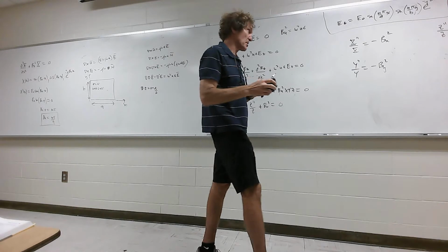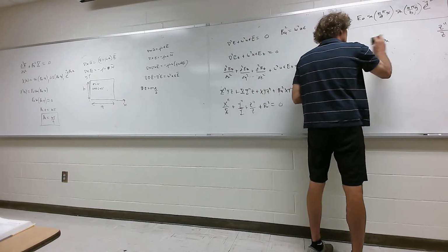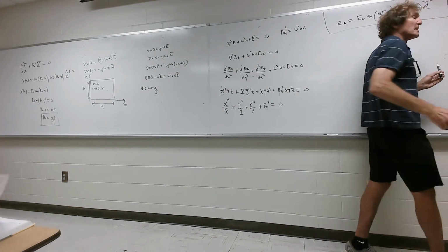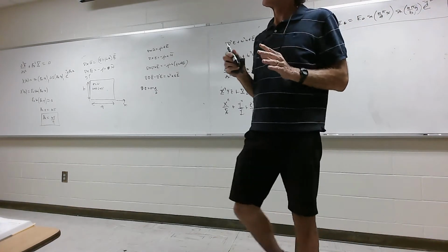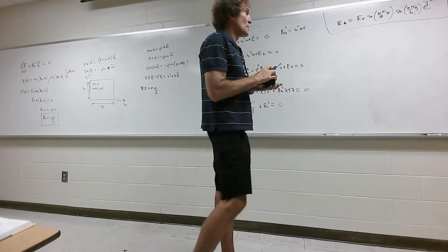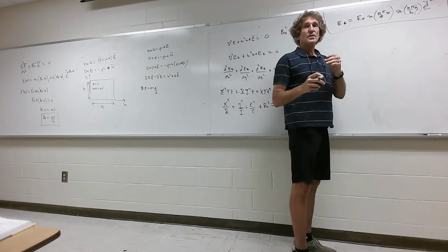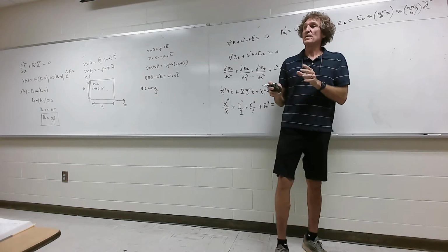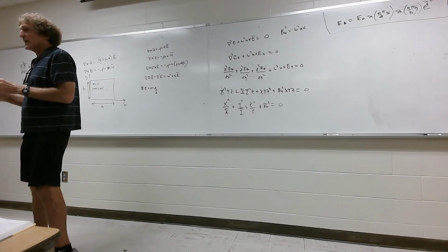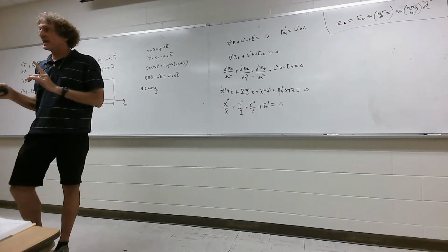It's real important to notice this. I've got to make a few comments about this. We'll get beta z in one second. Now listen, this is important. Remember, this is TM mode in a waveguide. When you take a look at this, the smallest possible value for m and n, where a mode can actually propagate, has to be m equal 1, n equal 1.